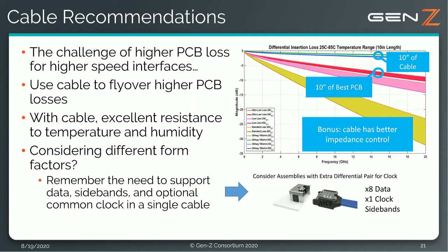Also, when we think about cable and making that connection across the backplane, you're thinking about the Gen-Z form factor or other form factors, we always have to think about having enough signals in that cable interface. So we think about our data signals, but don't forget about positions for reference clock, sidebands, and other things as we're making our selections and testing different cables over that front end topology.